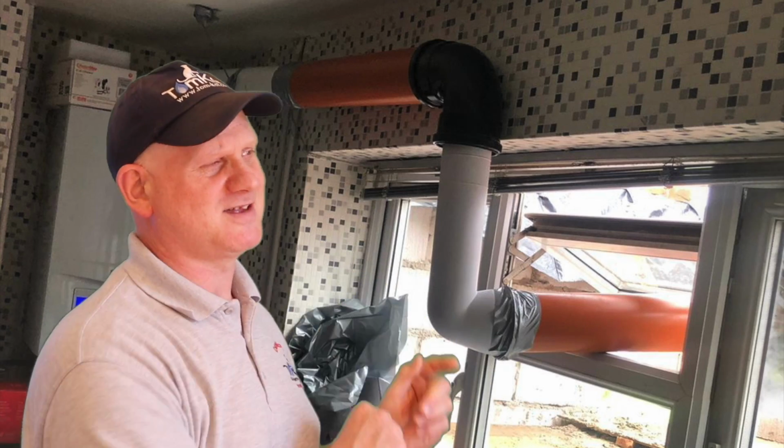But how would you classify this in the unsafe situations procedure? Now then, what have you classified this as? Because basically what they've done is extended the flue system out through the window using plumbing pipes, waste pipes. But they've also encased the products of combustion and the air in the same tube, and then put it out the window.